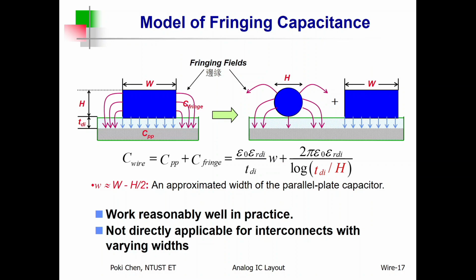The second effect for parasitic capacitance, we call it fringing capacitance, OK? At the boundary. So please keep this in mind. In the past, humankind only focused on this. That is in theory, parallel plate capacitance. But nowadays, fringing fields become more important than before. The more curvature here, the more energy you can store.